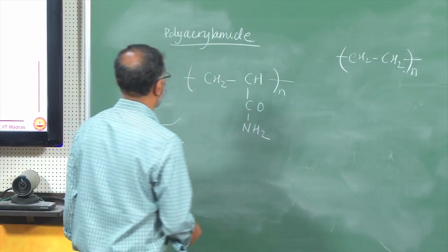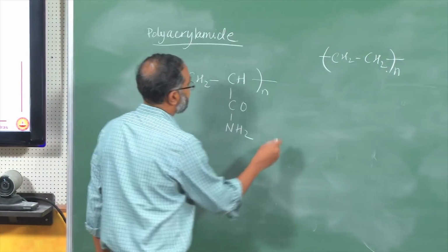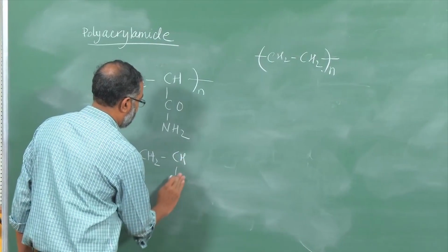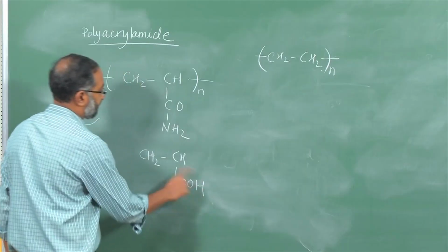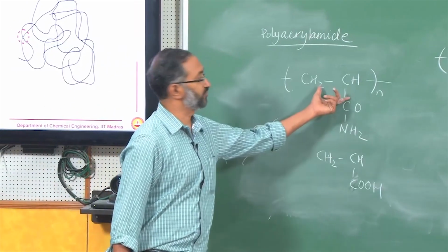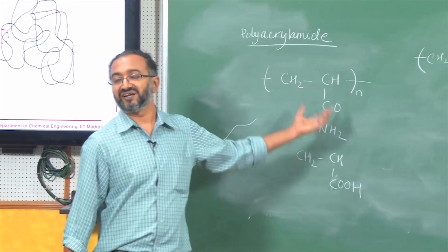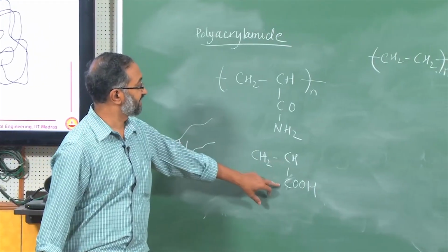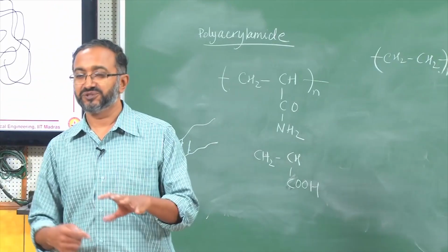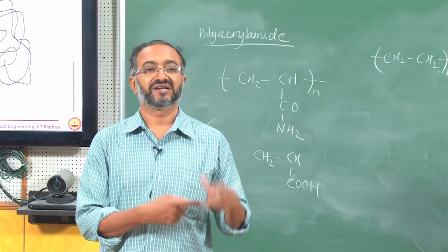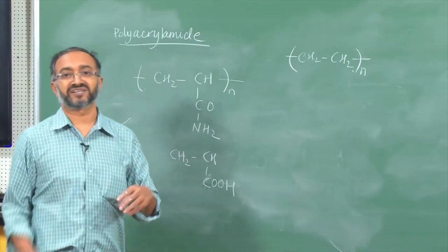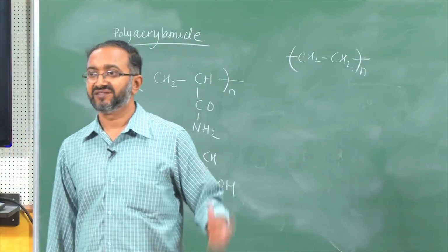Commercially available polymers have this, and some of the groups are basically this. So, this is the hydrolyzed part of the polyacrylamide. Some groups will have this unit, some groups will have this unit. That is called partially hydrolyzed, and you can see now that the interactions between this group and this group are different. Therefore, a partially hydrolyzed polymer solution will behave differently compared to a completely unhydrolyzed polymer. It has been found that the partially hydrolyzed polymer is more effective in removing the oil.